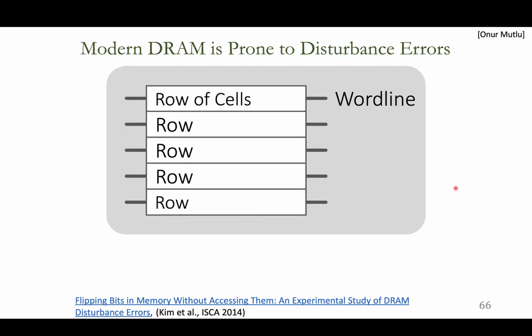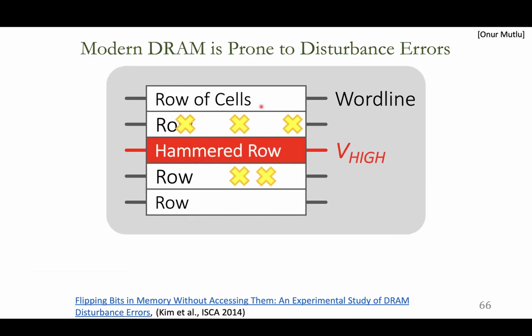And we also studied an error problem of DRAM called row hammering. If we continue to open and close a row, their neighbors will suffer from large bit error. They are victims. So the current DRAM manufacturers developed their own solutions to address the row hammering problem. Inside of DRAM, their solution is realized.